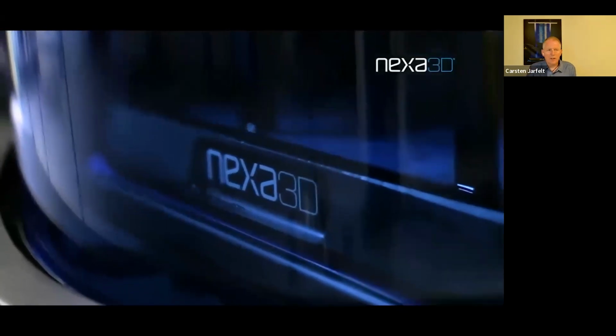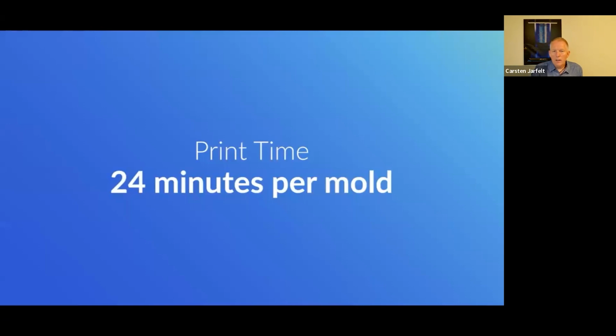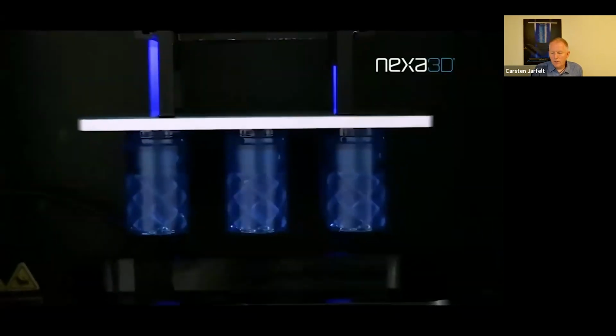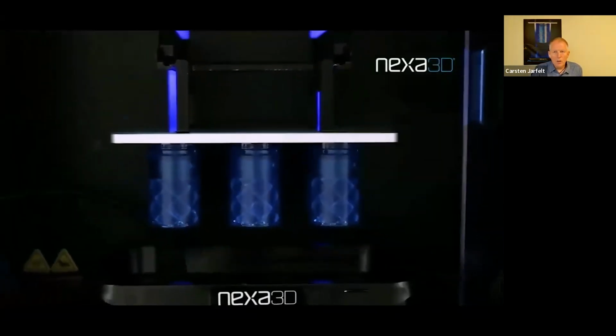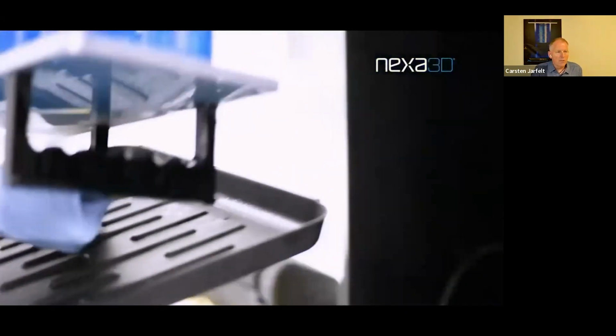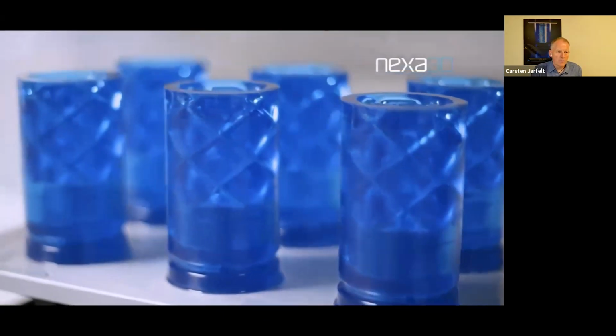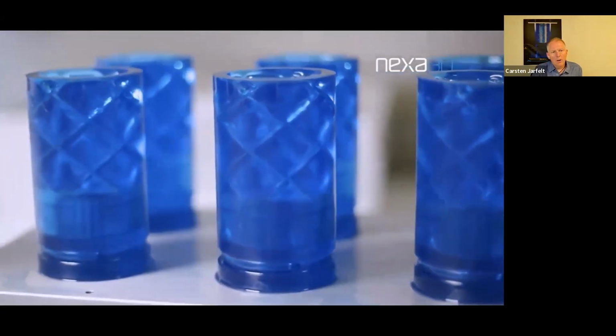Now you have your printers and the resin xMOLD, and now you will print tools. You can do that in whatever format and size and volumes that you want. And the xMOLD resin prints on average 2 to 3 centimeters per hour per full build plane on any of the resin printers that we have at Nexa.